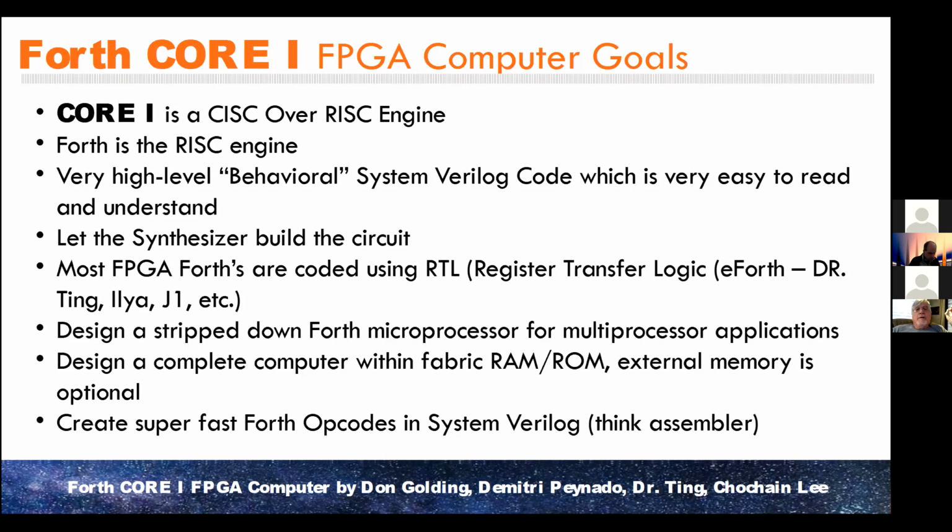We have a busy flag, and so if your opcode needs more time, it stalls the execution engine until it completes. This is going to be really important for allowing you to create your own opcodes. You don't have to worry about timing.